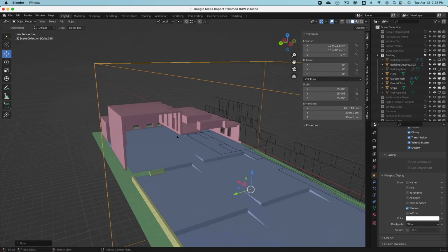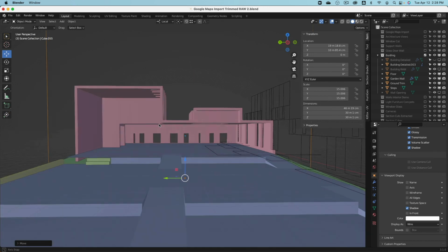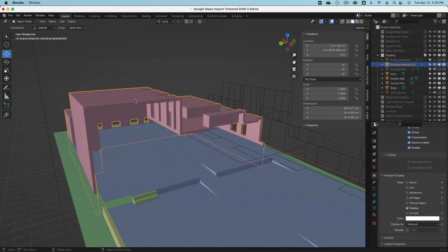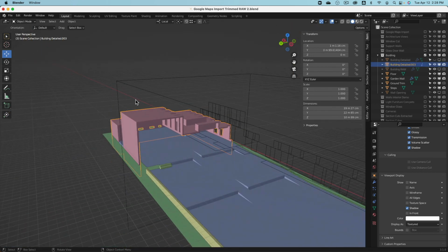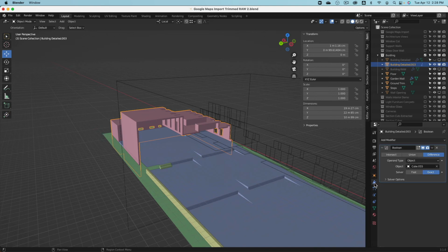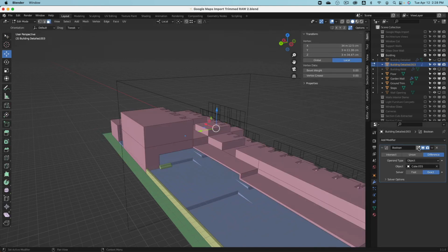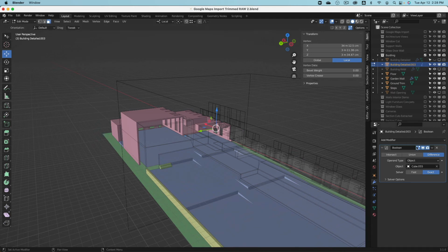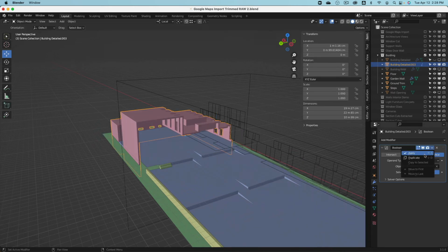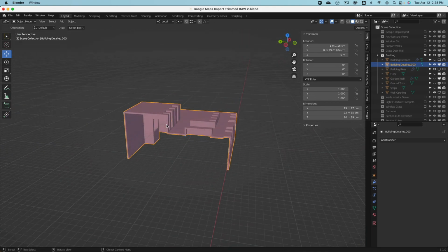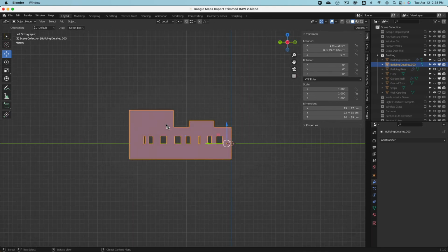So let's say like this. We would like to create an elevation view of a section from there. How can we do this now? That's kind of like the last step. It's also pretty easy. So this geometry now, because it's in real time, you see I cannot select the faces. I will have to apply this modifier. Apply. There's now my geometry. That's the reason why I made a copy.